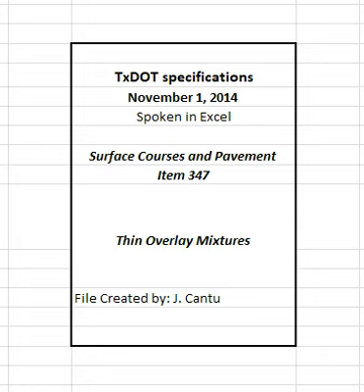The department may require the contractor to reimburse the department for referee tests if more than 3 referee tests per project are required and the engineer's test results are closer to the referee test results than the contractor's test results. The construction division will determine the laboratory molded density based on the molded specific gravity and the maximum theoretical specific gravity of the referee sample.